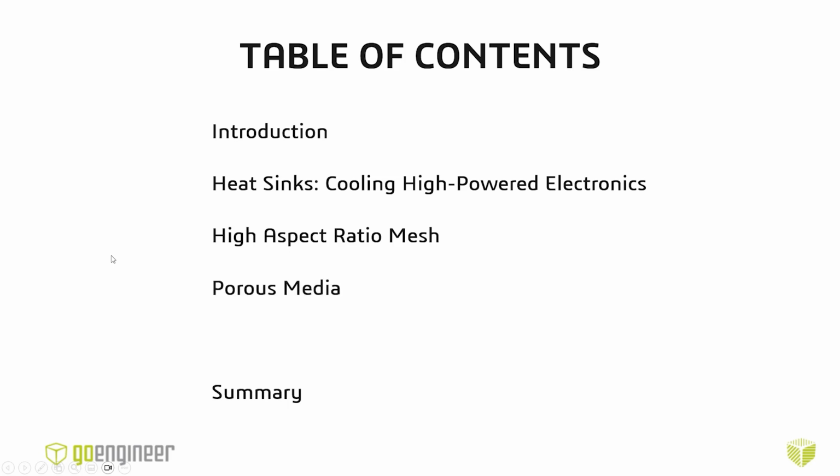We can also try replacing the heatsink fins with porous media. This is a three-dimensional block representing the fins. I can use this and still achieve pressure drop and heat transfer with a far simpler CFD model. And then if it gets too big to solve on a local computer, I do have some methods with cloud computing that we could look into.